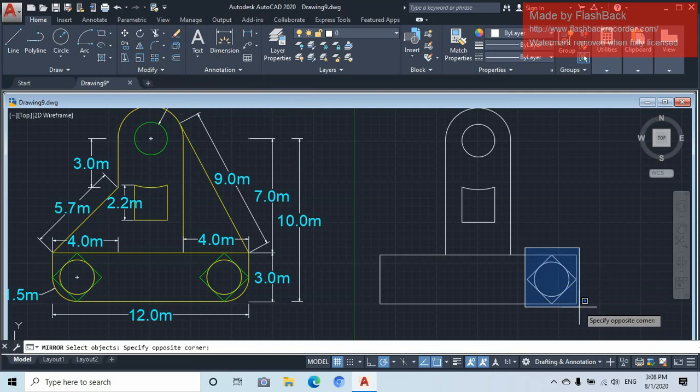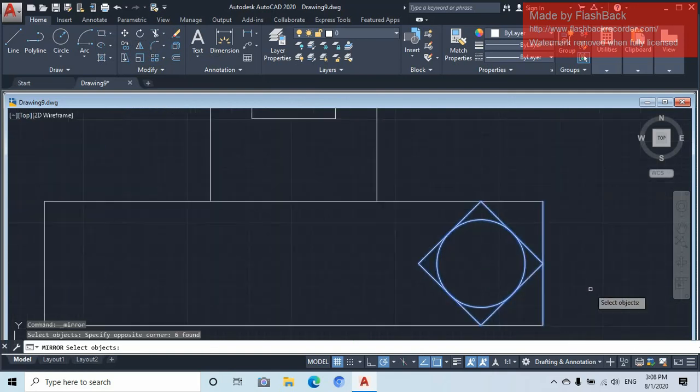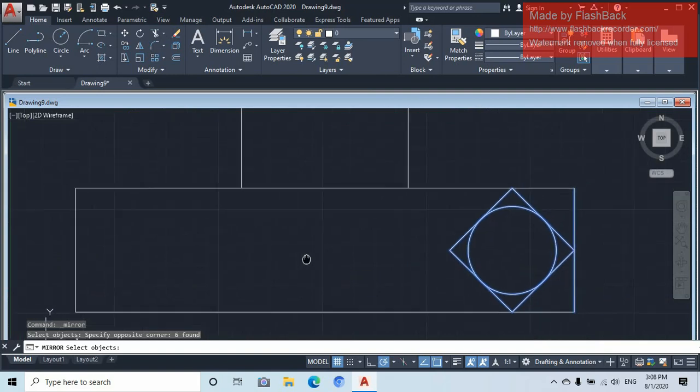Then you left click. Then you're gonna see that when we do our offset, this line is gonna appear this way. So we're gonna have two lines here, but we are gonna delete it immediately after that. So now you press the enter, then you come here, hover your cursor here, it's gonna snap at this midpoint.